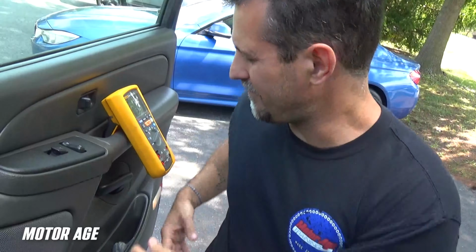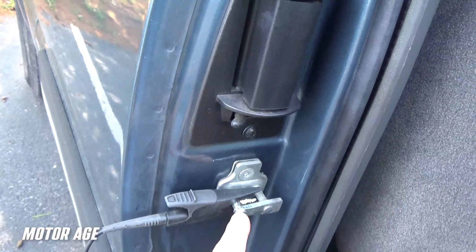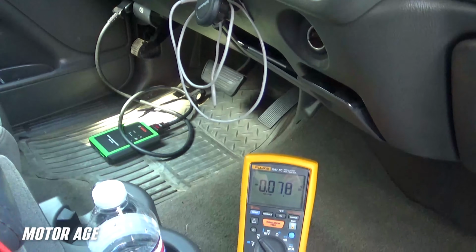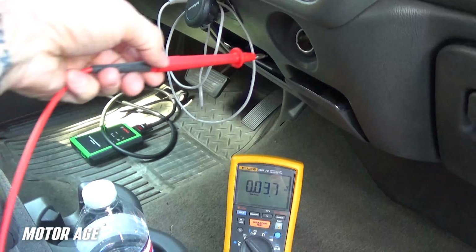And that answer is always going to be whatever's easiest to access. So the first thing we're going to have to do is test our equipment. I'm going to reference my DVOM to a known good ground and voltage supply and make sure it registers on the display what I anticipate. This way I know I can trust my equipment. I've referenced my ground cable to the vehicle's chassis, and we are going to test for adequate voltage supply at this auxiliary power source.